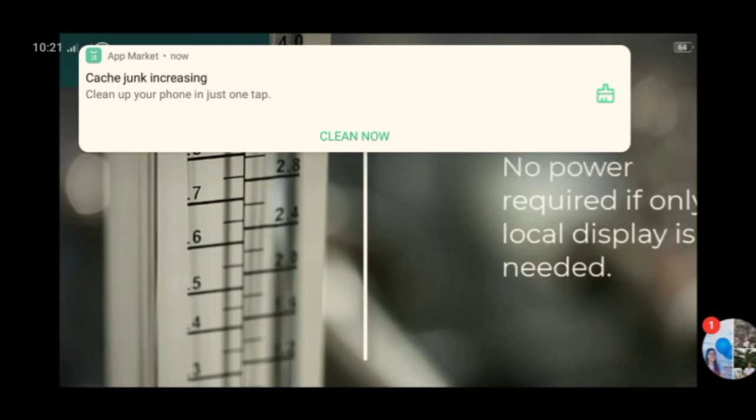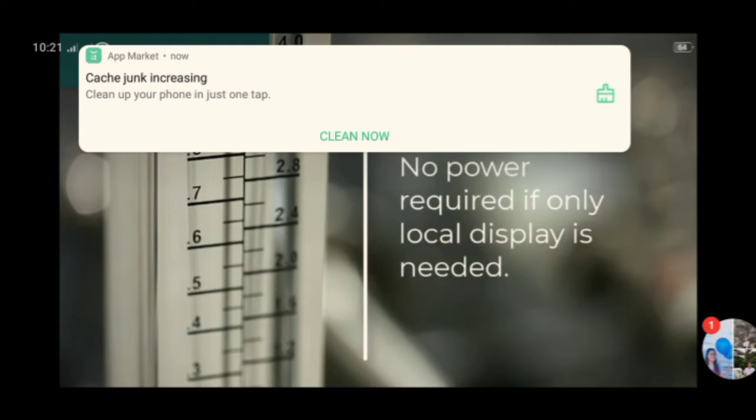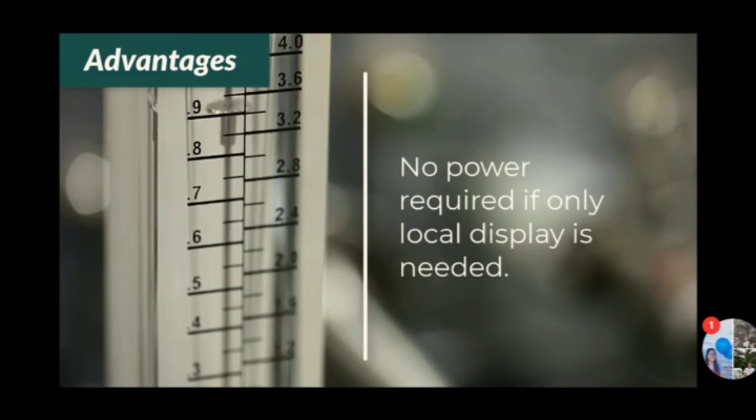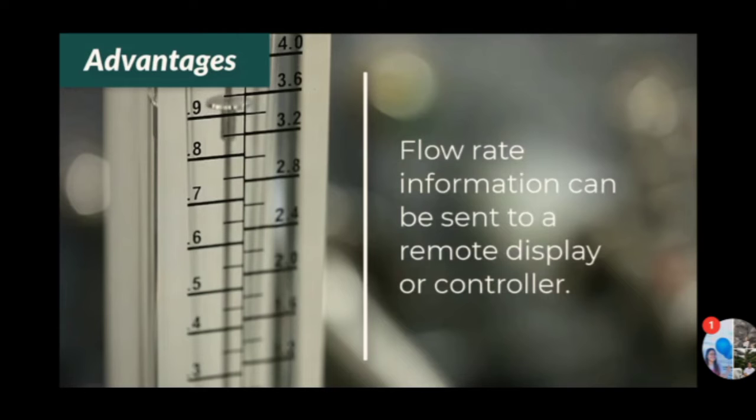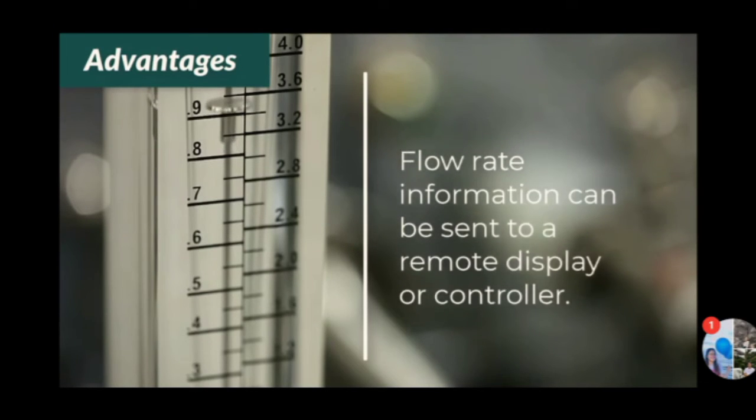If only local display is needed, no power is required as the float position can be seen through a transparent tube. The float can be magnetically coupled to a dial indicator, or an electronic transmitter can be used to send flow rate information to the remote display or controller.